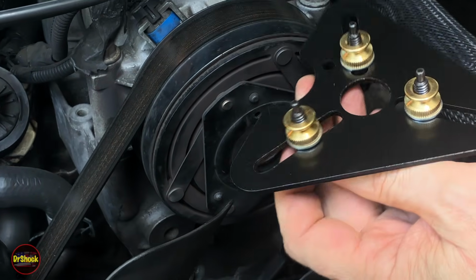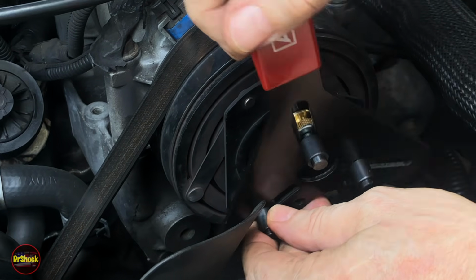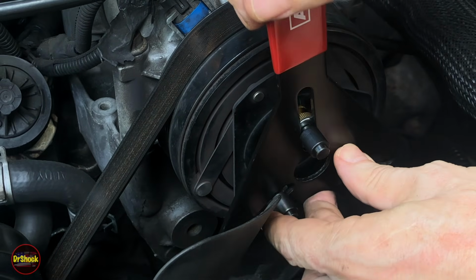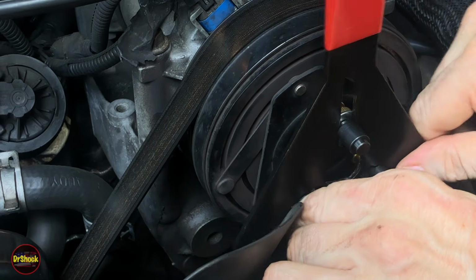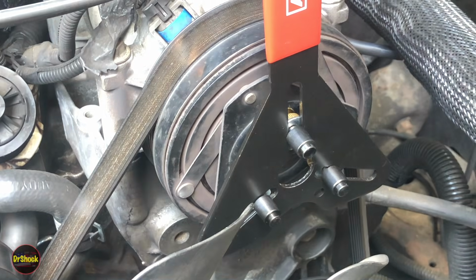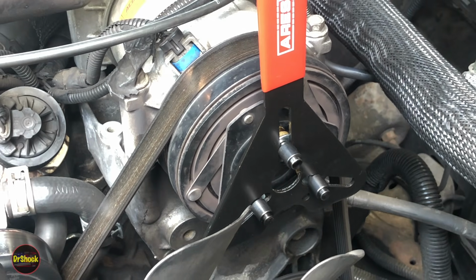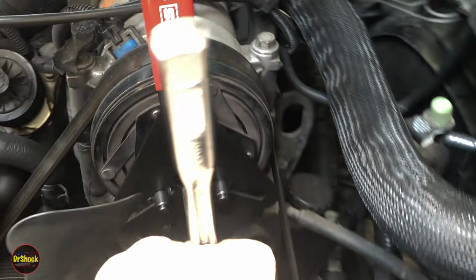On the back, you see there's these little prongs, and we're just going to get them lined up into the 3 holes. I usually keep one of them preset and aligned, and then the other one I leave flexible. All right, so now I'm going to go grab a 13 millimeter deep socket, and we can fit that right in through the tool onto this nut.